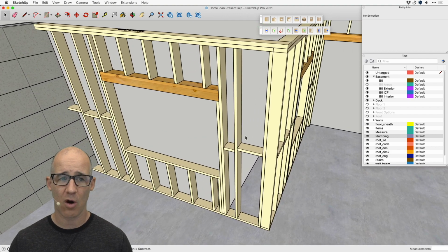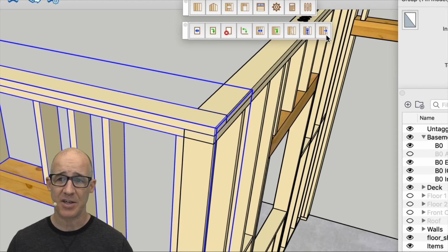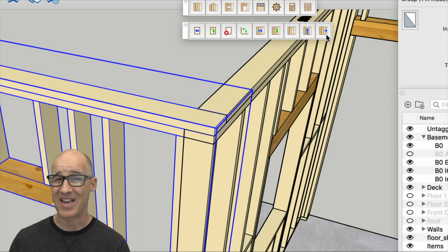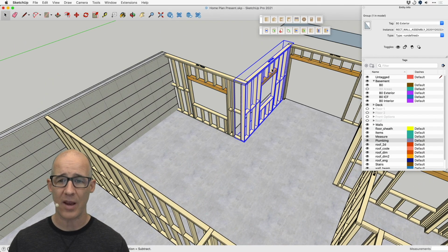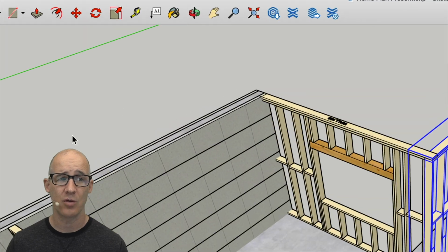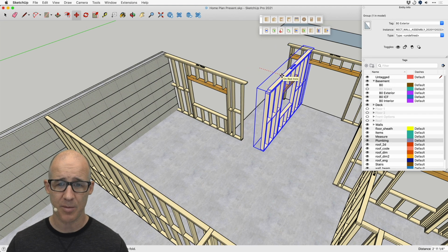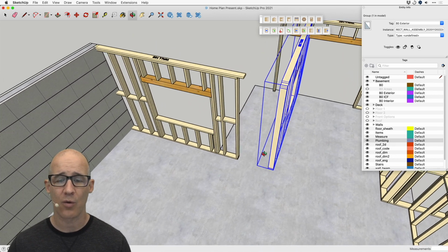So this particular wall, we'll go ahead and modify it. The extension is this option right here, and you can always extend a wall and then reconnect any other wall. So just like we did when I was showing you that you can move a wall regularly with the regular tool, let's go ahead and do that, but let's reconnect the wall. So I will move this with the regular move tool. Make sure I'm on axis right there. I've moved it, let's say, to a guide or relative to what I want.